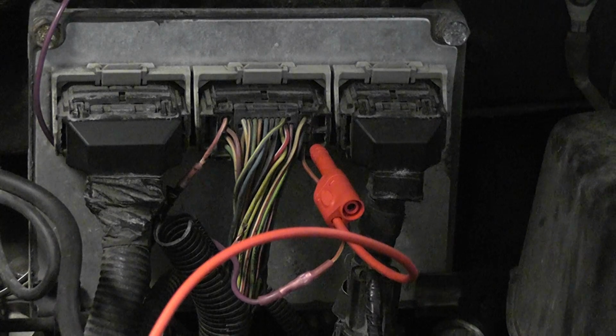If we have 0 volts on this wire, then we have to go into the harness further and find out where our problem is. I know these cars are known for bad coils. That is not the case with this car. It's already had coils substituted. It's had wires replaced. They're ready to call a computer. They bring the car to us. That's where we're at. Back to the board.